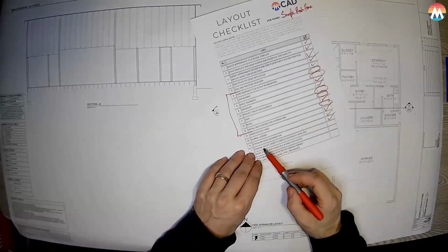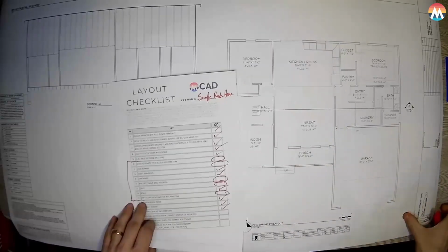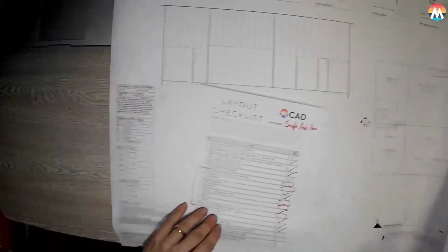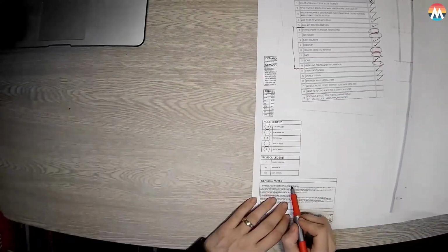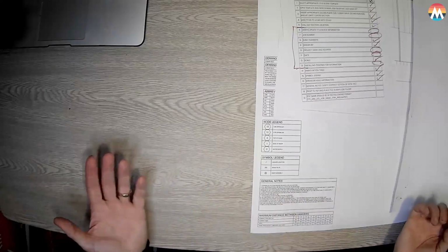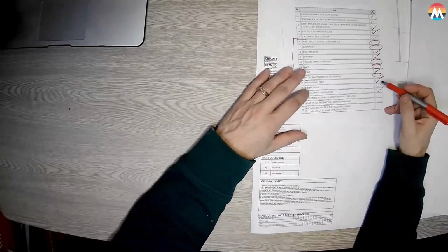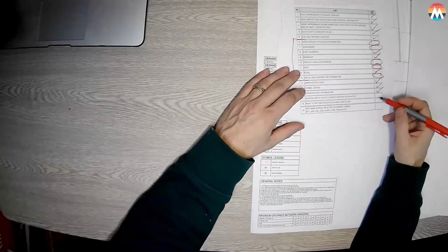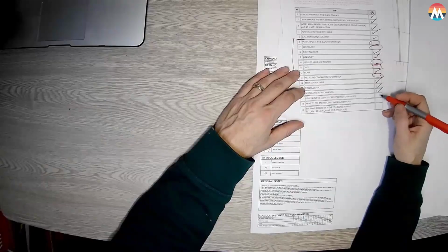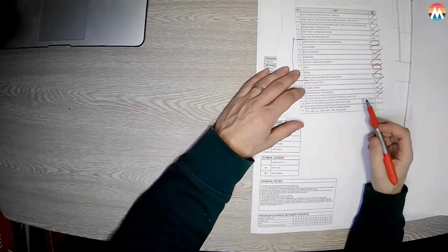All right, general notes. Verify correct edition of NFPA 13B. So over here in the general notes, this says 2019 edition because that's what we are here in Oregon. California's already passed that. Lots of other places are too. Some are behind, just depends on what part of the country you're in. But that's something you want to double check. So based on our area, we've got that correct.